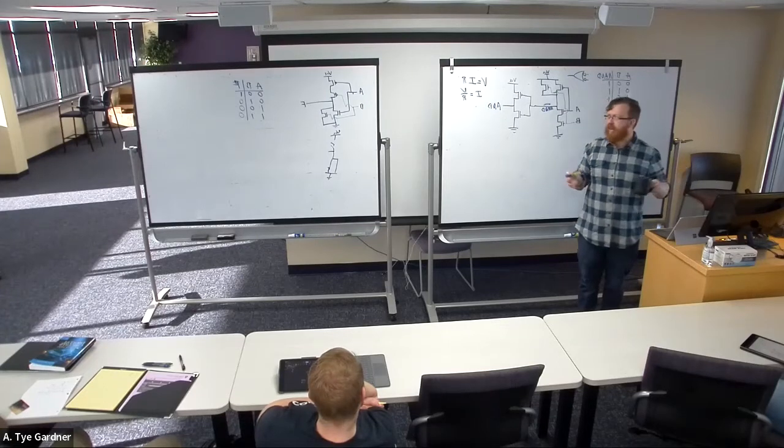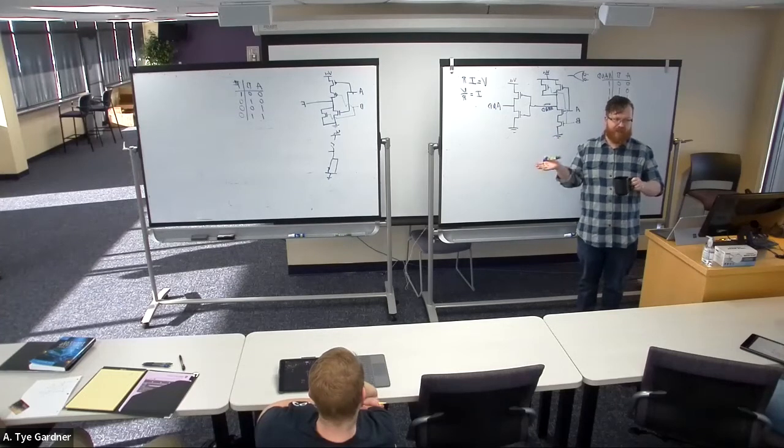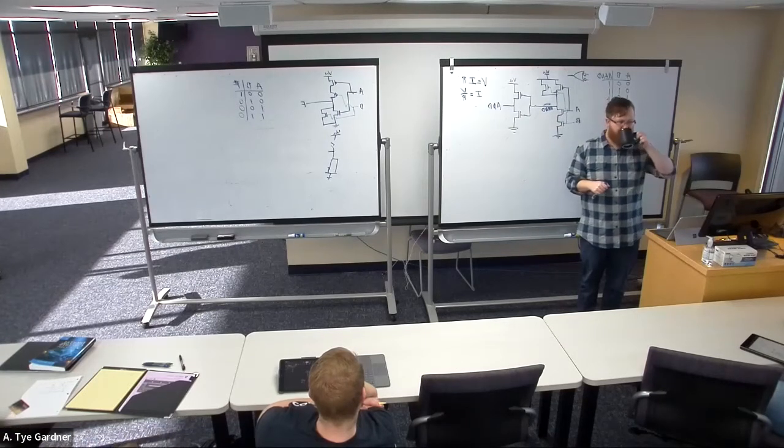And then we usually pick either NAND or NOR rather than both just for the scalability, right? We choose the NAND or NOR, the universal gates, because of the size, and then we stick to just one or the other for scalability and affordability.